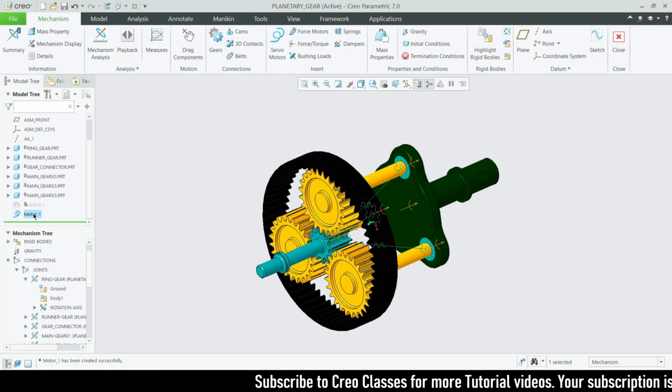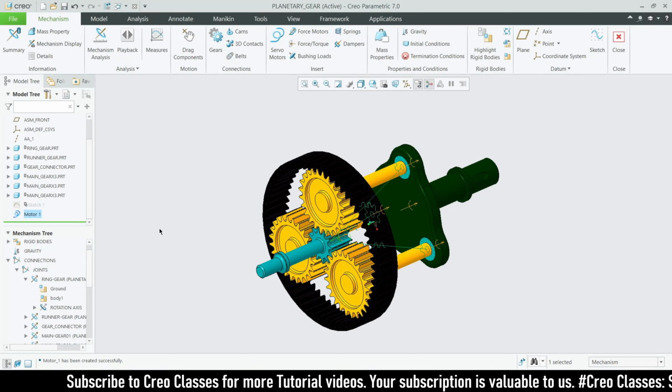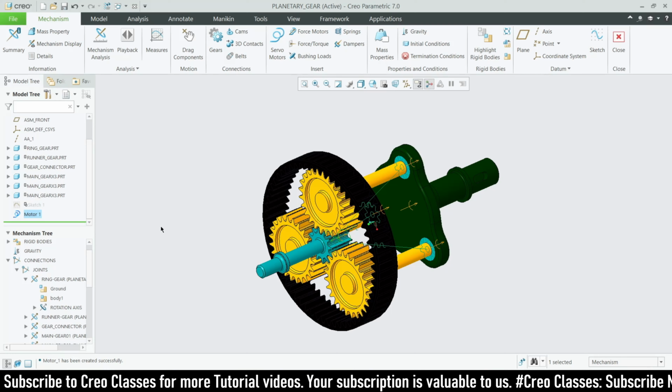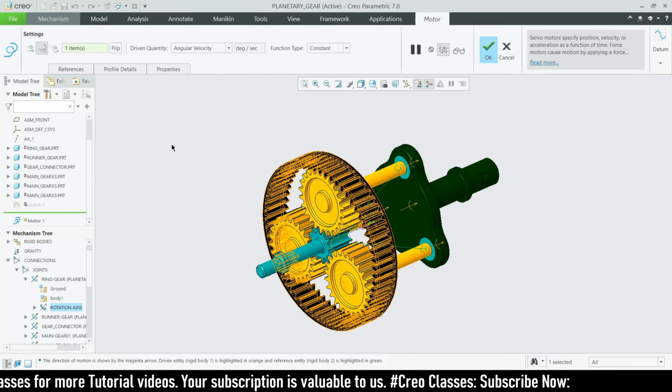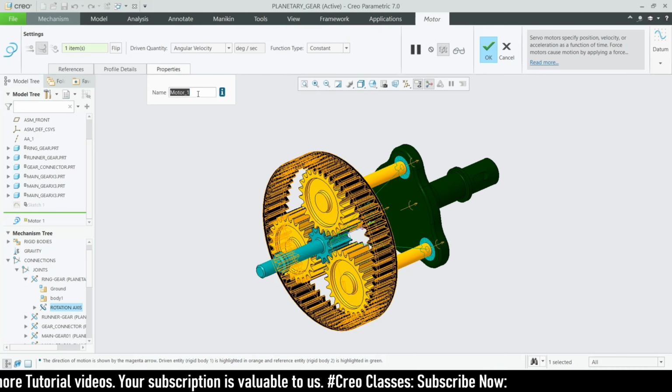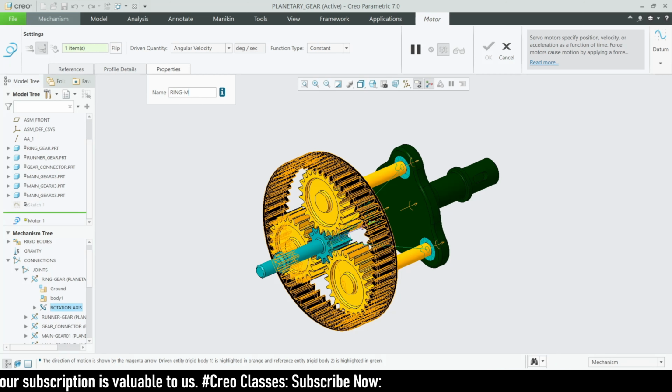So now here we have motor 1. Like that we have to create around 6 motors. If we have motor 1, motor 2, motor 3, that will be very difficult. So I'm just going to rename this. Go under the properties. I'm just going to rename this. So this is going to be the ring motor, right? So ring motor. Done, and click on OK.